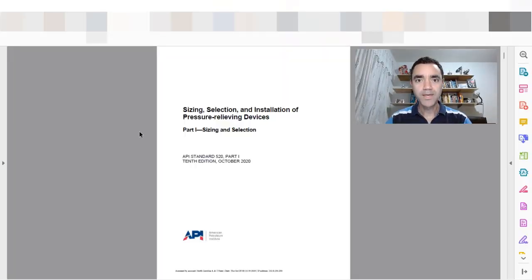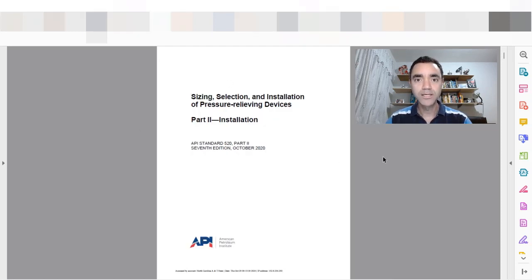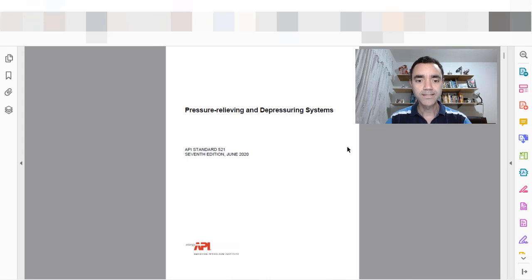Talking about API 520 Part 1, it is related to the sizing and selection of the orifice of your pressure safety device. In Part 2, you will find recommendations for installation of the PSV and other process safety devices. And it is in API 521, which talks about pressure relieving and depressuring systems, that you find the procedures to estimate or calculate the required flow for the definition of a pressure safety device.